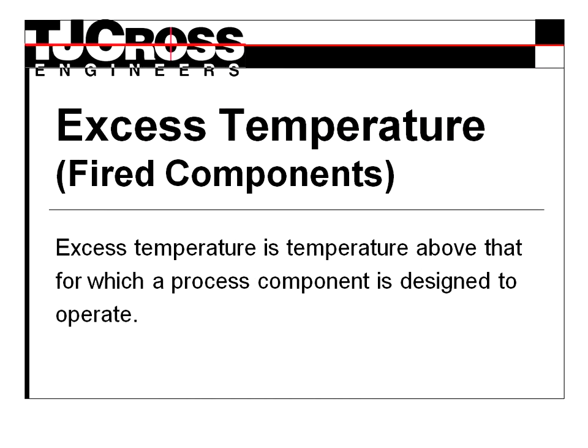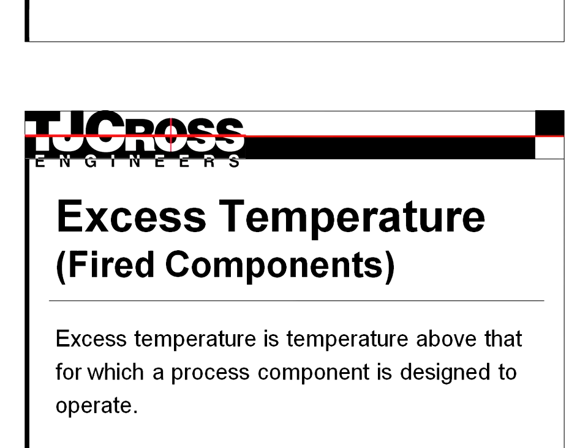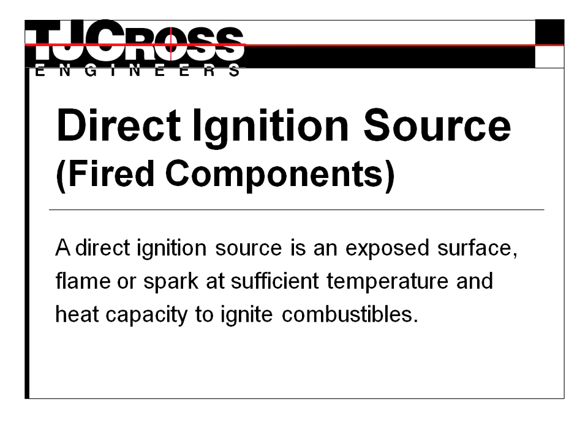Excess temperature for fired components. Excess temperature is temperature above that for which a process component is designed to operate. Direct ignition source for fired components. A direct ignition source is an exposed surface flame or spark at sufficient temperature and heat capacity to ignite combustibles.